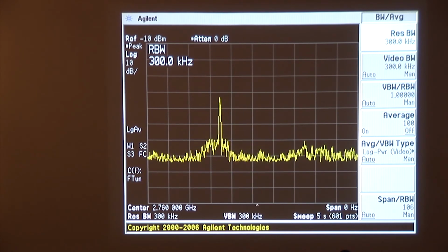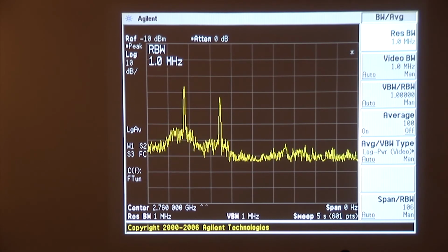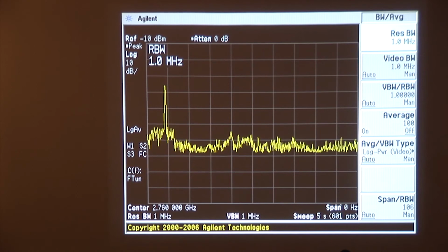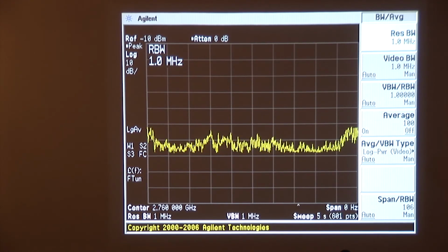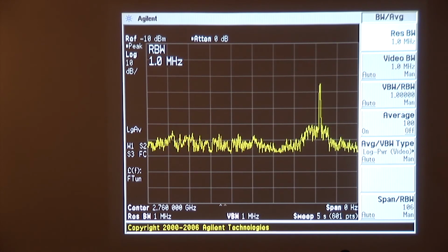So we'll take the bandwidth back up to 1 megahertz, and this is the point where we get the optimum dynamic range, where the noise level is as low as it possibly can be relative to the power that we're getting out of the radar. Now, if this were an actual field site location, we would have also worked to optimize the measurement system's location on the ground, as I said earlier in the whiteboard section of the talk, and we would hopefully be getting about plus 30 dBm.